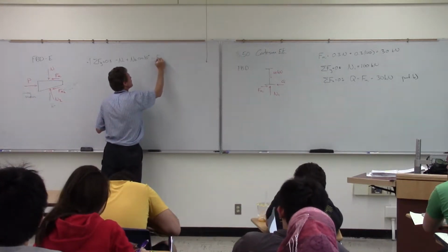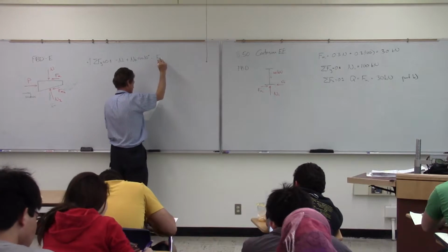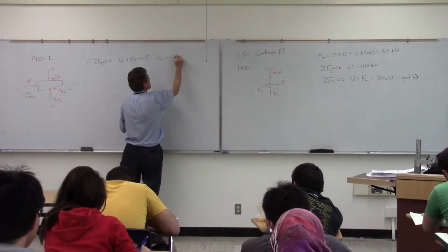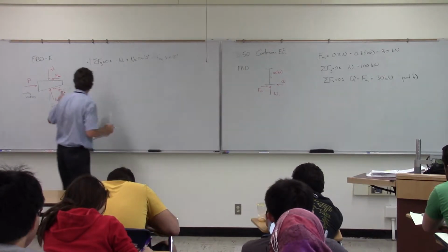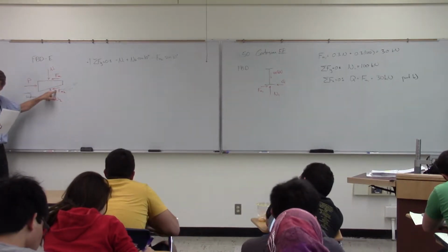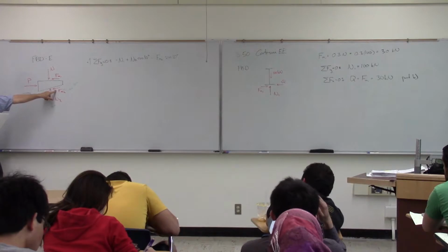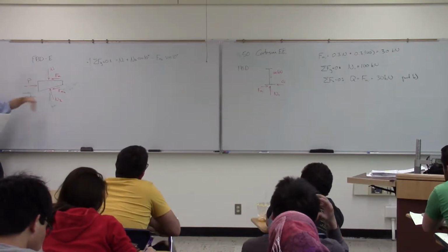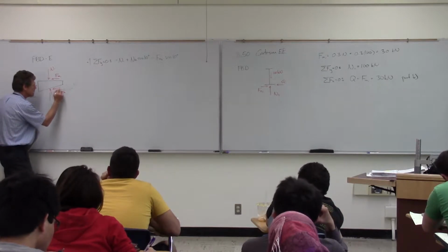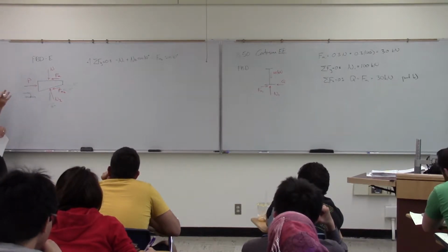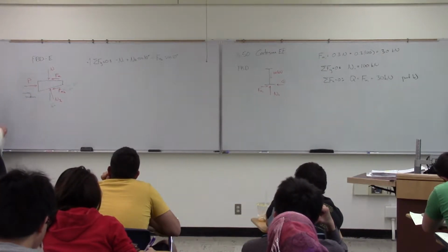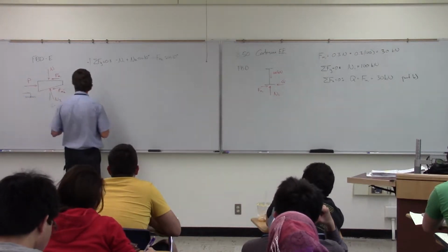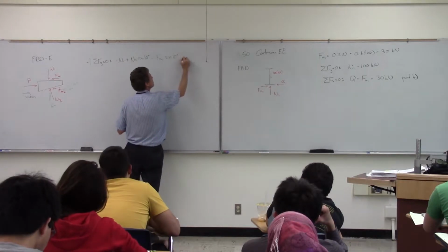And the one thing everybody forgets is we also have a vertical portion on the friction force. And the way I've got it shown here is that it will be acting in the opposite end. It'll be acting down. So the vertical portion of that is acting down like so. Small, but still we have to account for it. And that's everything in the vertical direction.